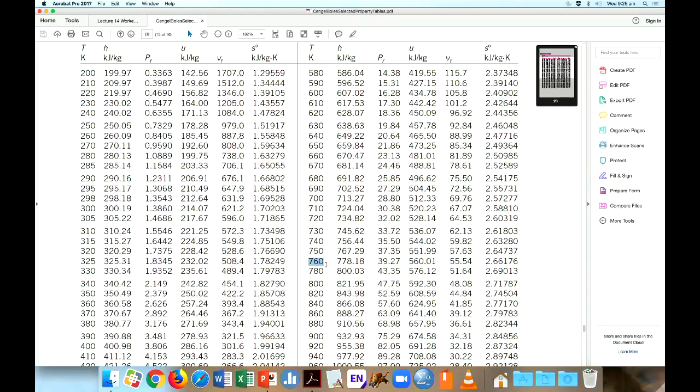When the whole cycle is analysed and you come back to the starting point, often the errors cancel out. So one of the reasons why you'll find us using constant specific heat is because the analysis for one component might have an error, but by the time I've gone up and back, those errors can balance out, but not always. So keep an eye open for when I'm saying constant specific heat or variable specific heat. That's your trigger to say I'm using a table or an equation. All right, let's get back to the notes.